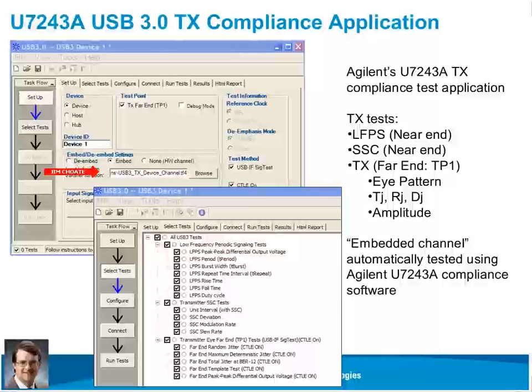One thing to note, a lot of early silicon had the option to turn SSC off. This is still allowed due to a backward compatibility problem with early hosts that shipped that had a problem with proper implementation of SSC. So I always recommend designers to include the mechanism to turn SSC off. It's required for certification testing to verify that you meet the requirements when it is turned on, but people are allowed to turn that off to solve this interoperability problem with hosts that had center spread SSC.